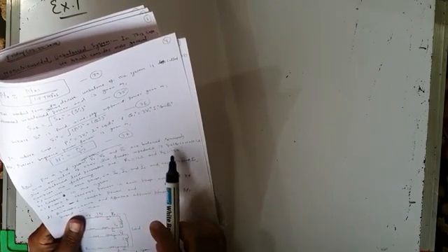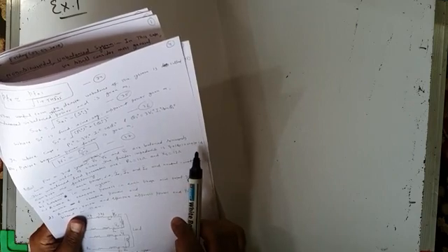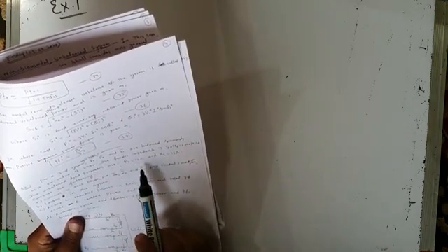It's written that for a three-phase system shown below, I will draw the three-phase system in a moment. VA, VB, and VC are balanced sinusoids with RMS value of 220 volts. The feeder impedance is RF plus jXF equal to 0.02 plus j0.1 ohm. The unbalanced load parameters are RL equal to 12 ohms and XL equal to 13 ohms.